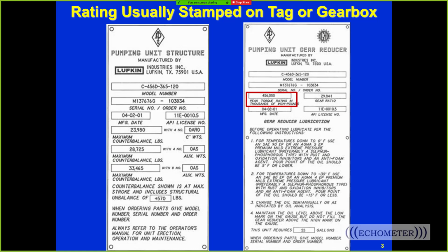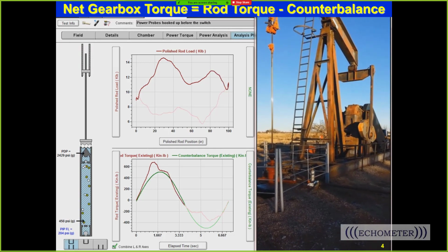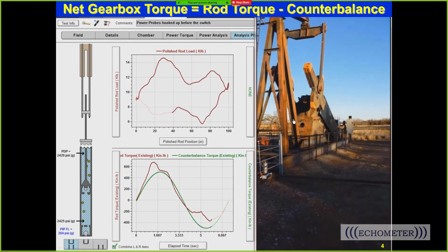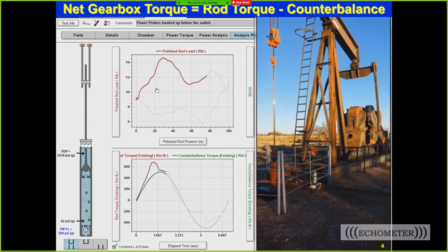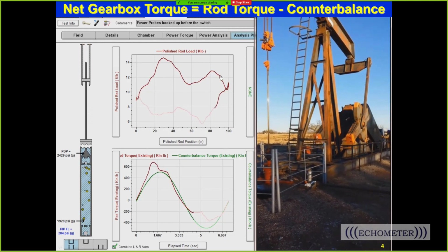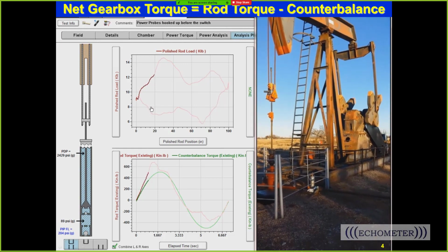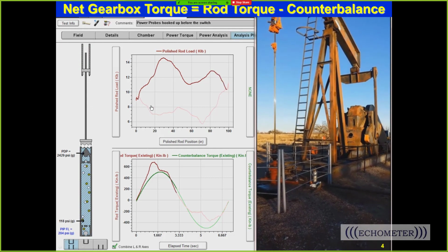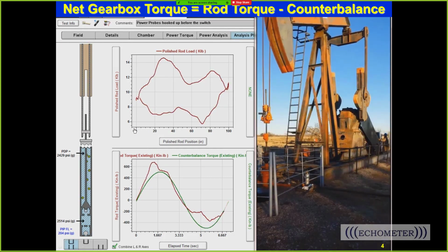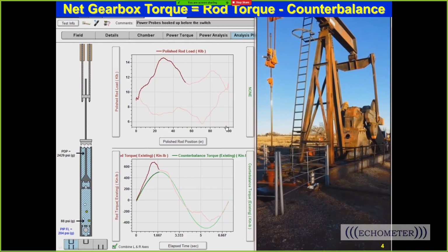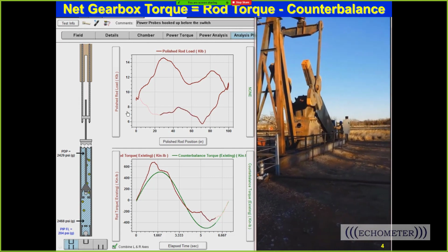gearbox sometimes. Now this is a video that is synced with the pumping unit, and we're measuring the polish rod load and position here, and that's real time that we did that. And this is the surface dynamometer card. So here's the upstroke load, and then there is the downstroke load. And so the dynamometer card is part of the mechanical torque calculations. This is the stroke length here up to 100 inches for this pumping unit. And this is a load in thousands of pounds.